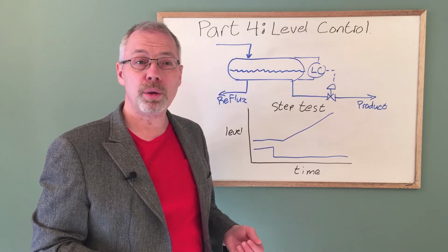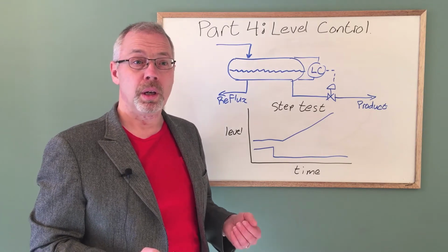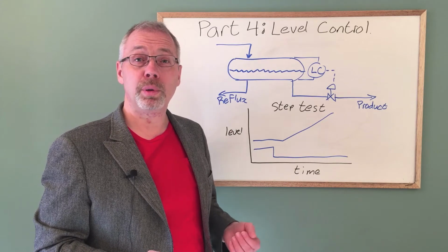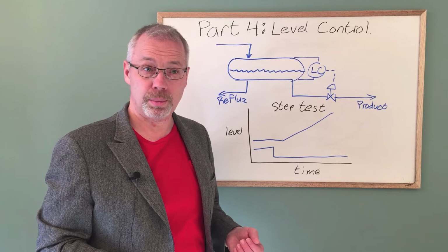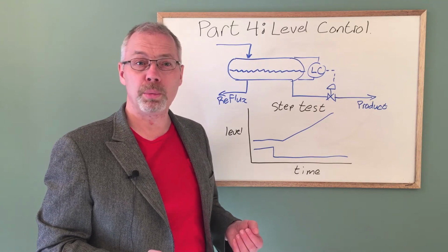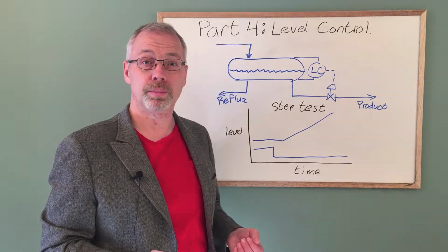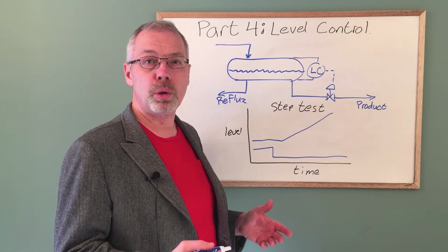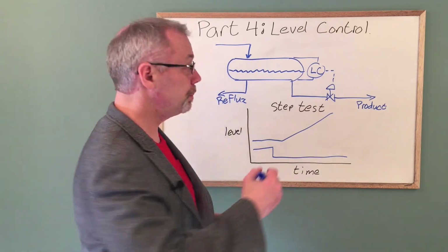The important thing to note is that this is not a stable or self-regulating process, like temperature from a heat exchanger. In this case, the level will rise indefinitely. This is a non-self-regulating process. This often causes problems where people are used to working with self-regulating processes. We define the process gain as the change in slope that is produced by increasing the valve position by 1%.